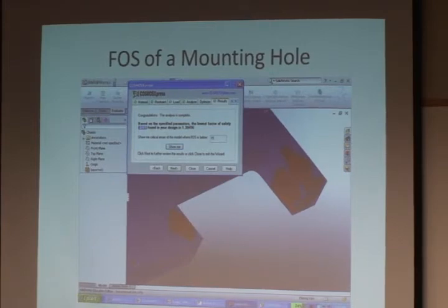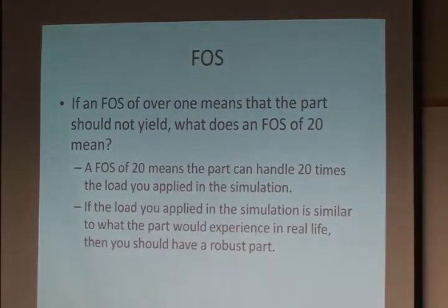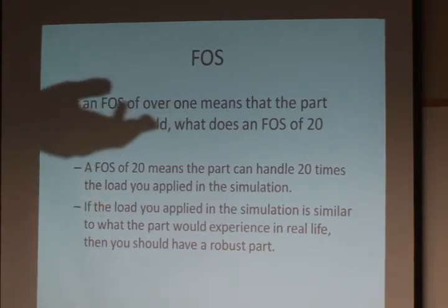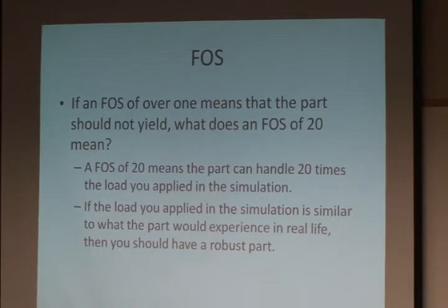So, yes. Something that's really important, I don't know if you're going to get to this, is the idea of optimization. So if your number is like 15, you know that the material that you're using with your design is way overkill. So you know that you can sacrifice taking weight off and adding it to another location on the bot where you think would be more appropriate. So if you're getting a number like that, optimization is a big part of it. Absolutely. So if it's a giant number, like he said, 15 or 20 times, you know the part's way overbuilt. You can go with it if you have the weight to work with. If you don't have the weight to work with, that's a good place to take it out. But more FOS is better. The greater that number is, the less likely it is to fail.